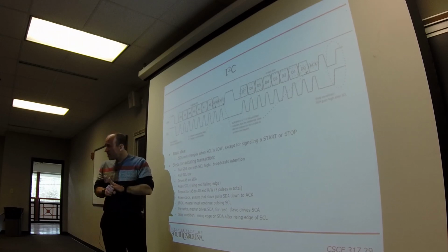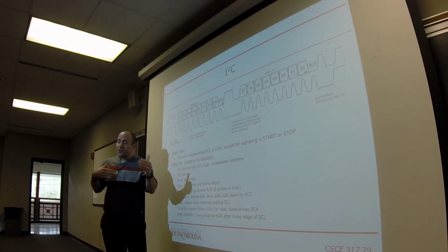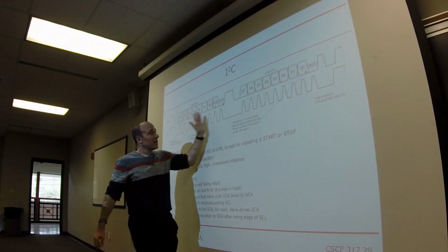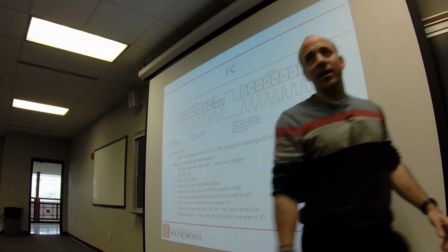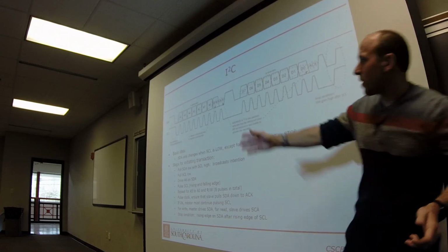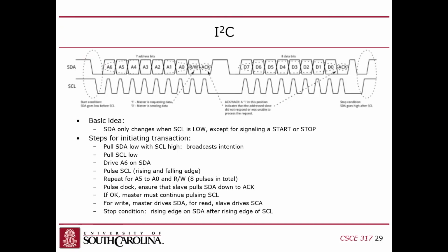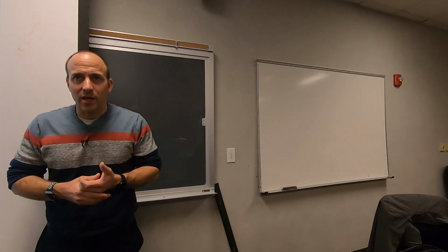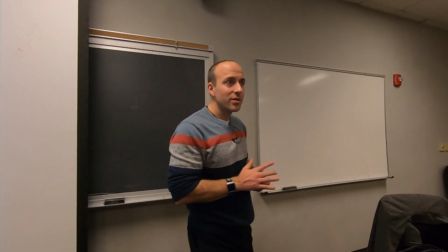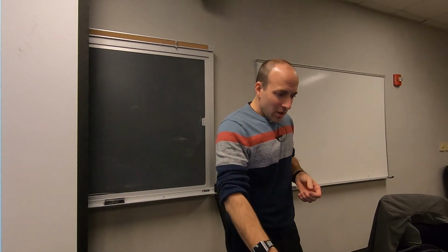Make sense? So then obviously, like I mentioned, if it's a read, then the other side is going to have to do his pulsing and send the data back, right? And then I'll have to acknowledge that, right? Or if it's a write, then whoever initiated it will have to send the data that he wants to write. Again, it's all byte-based, so the address plus the read or write flag is a byte, and the data is a byte. Or sent in bytes, I should say. And every byte is acknowledged. Any questions? Okay.